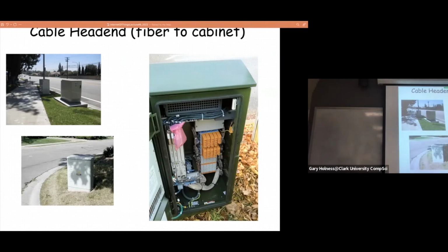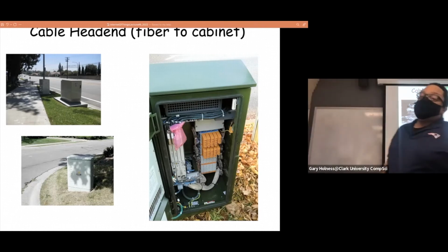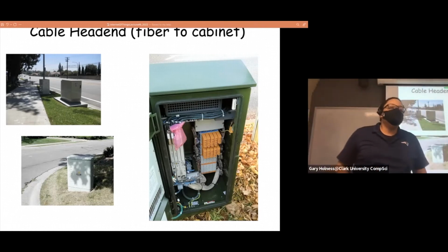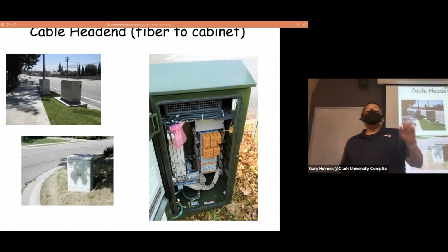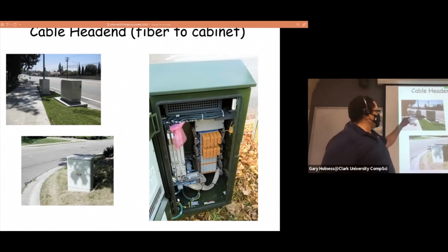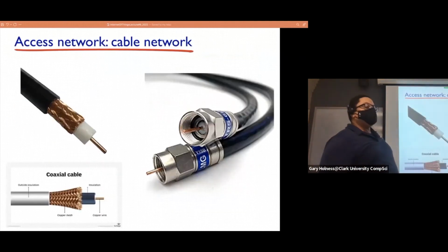But inside of these cable headends, you have the translation to get from pulses of light, or ones and zeros, to electrical energy on coaxial. And it's the coaxial cable emanating from these head-end devices that serve the individual houses. So if you have a cable modem type of internet residential setup at home, or a parents' home, or a friend's house, and you look in the basement somewhere, you will see your cable box, and you'll see this coaxial cable emanating from it.